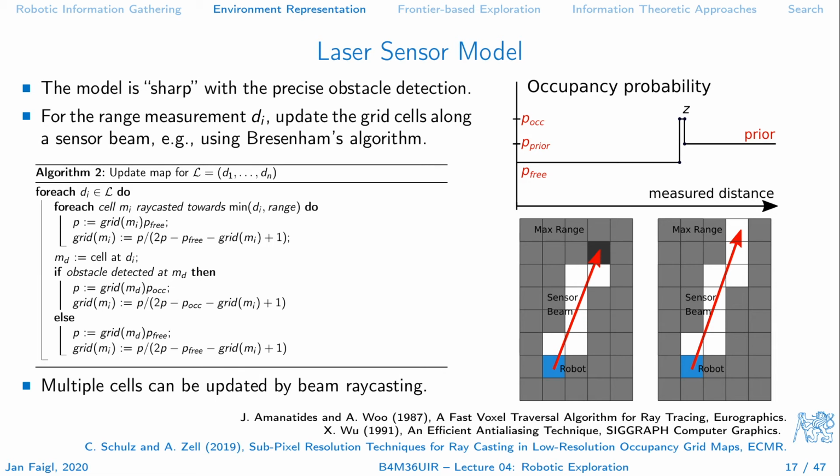So we can consider, okay, this is the point, but in fact we measure by laser beam some surface, and it is reflected in the direction of the surface normal. Okay, but basically what we can do with this laser, a very simple technique, is that in our grid map we can actually raycast a line or straight line segment and update these cells.